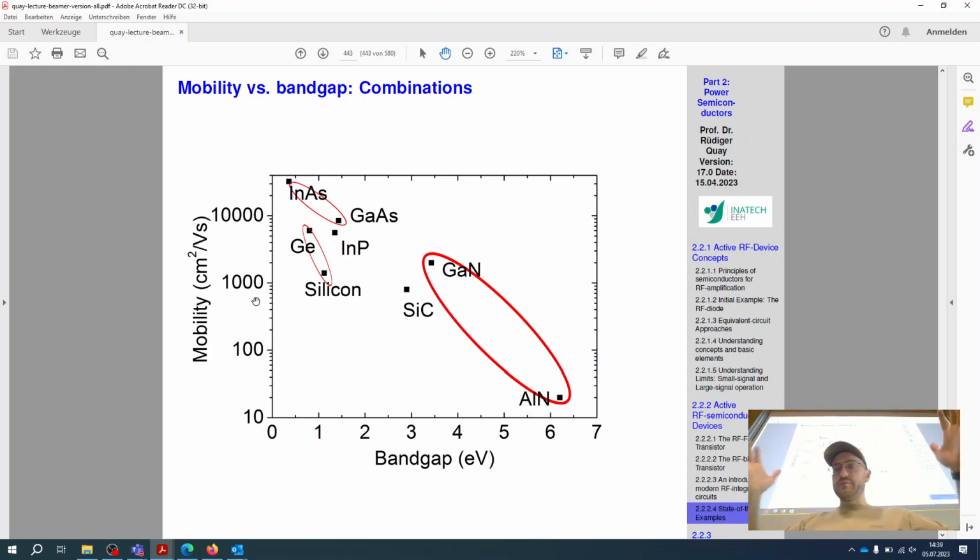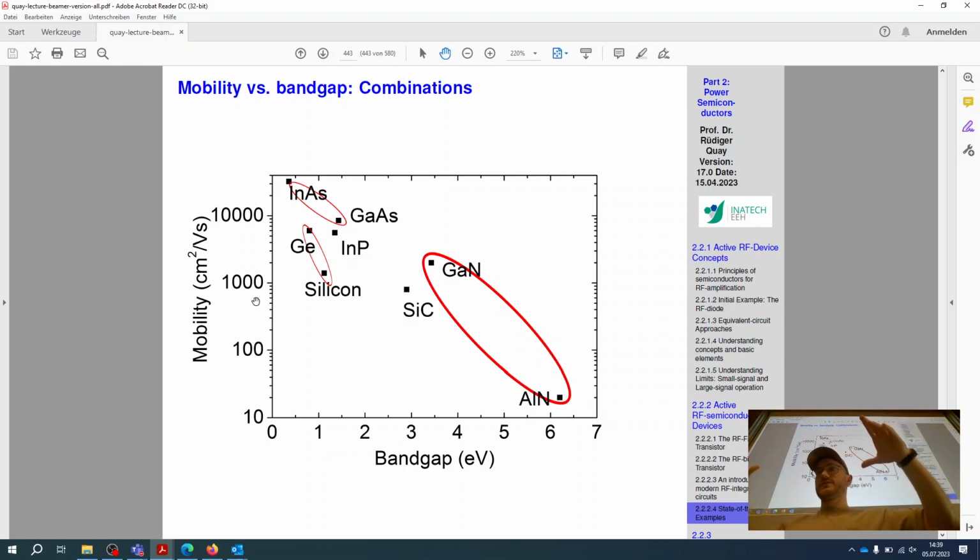And so forth. Usually it's a battle between the technologies. Nowadays, I think SiGe, GaN, and GaAs are what are mostly used in the world of amplifier design and power devices. GaN inhabits the world between 0 and 200 gigahertz, the area where the power density is the highest.